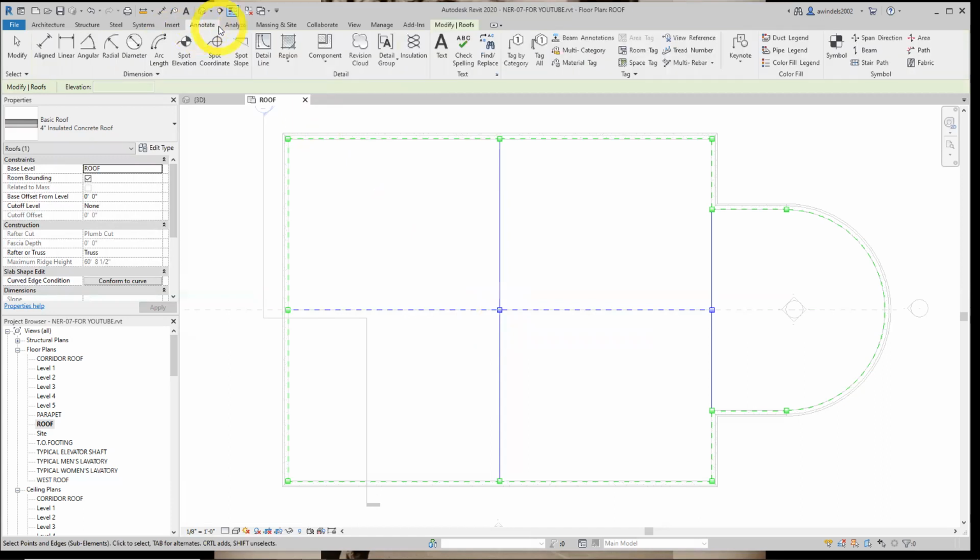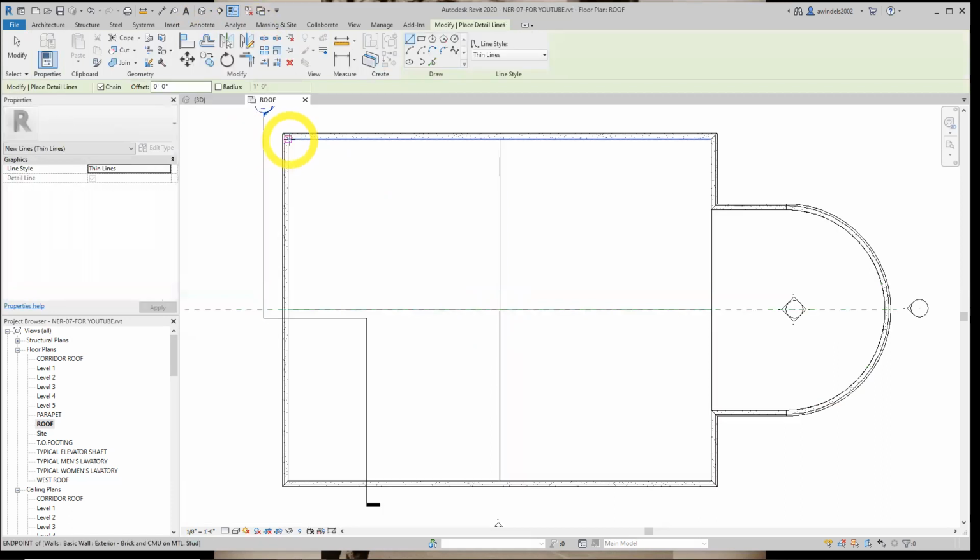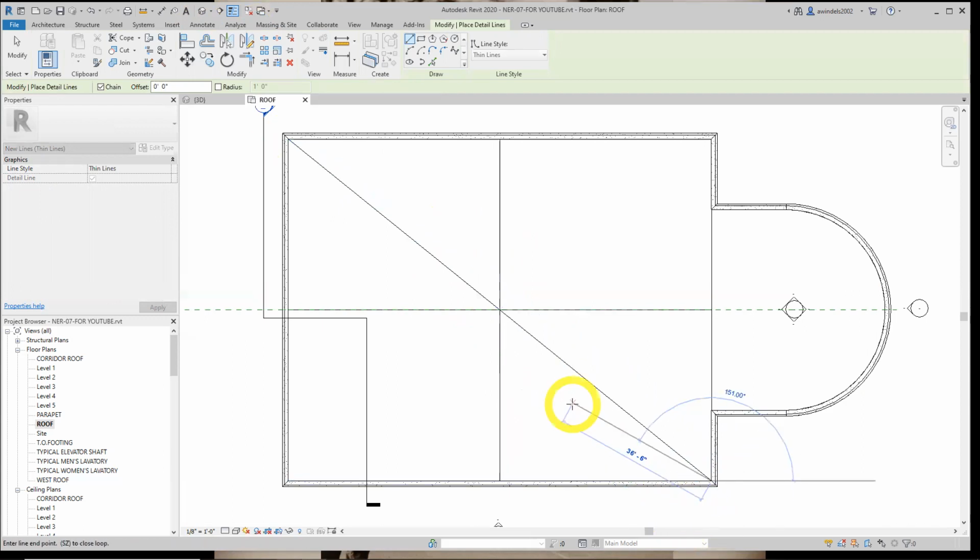I'm going to keep going with this, and I'm going to do this detail line button while this is going. So my splits did happen. I just exited out of sketch mode. I'm going to do 4 lines. 1 there. Continue this one, but I did snap it there already. Square endpoint snap. Same with this one. Escape.